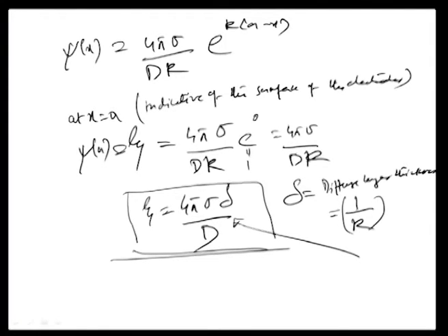This is a very critical value which matters particularly in electrochemical machining processes, because every surface would have a characteristic zeta potential with respect to the electrolyte of interest that you are flowing in, and that zeta potential has to be somehow crossed over by the applied external potential in order to furnish the electrochemical machining operation. And so, the zeta potential is absolutely important to keep in mind to estimate things like material removal rate, etc., which happens normally during electrochemical machining.